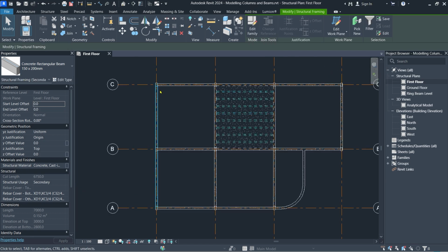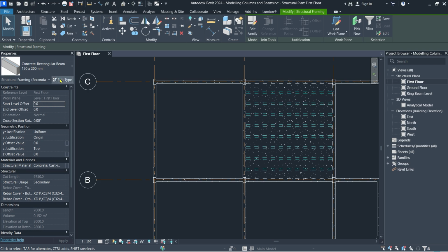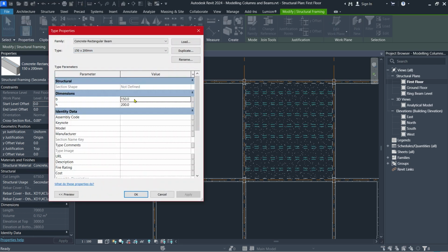For example, if I want to edit the rib breadth to maybe 1 to 5, you'll notice that they will want to shrink in a bit, like that. I want to make them a bit wider and deeper. Let's have a more significant load than usual, like that, and press OK.